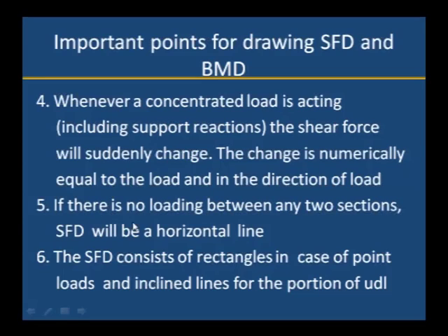Then if there is no load, the shear force will be horizontal. Shear force diagram will be a horizontal line. The shear force diagram consists of rectangles in case of point loads and inclined lines for the portion of a UDL. If it is a point load, then shear force diagram will be rectangles. If it is a uniformly distributed load, it will be inclined lines.